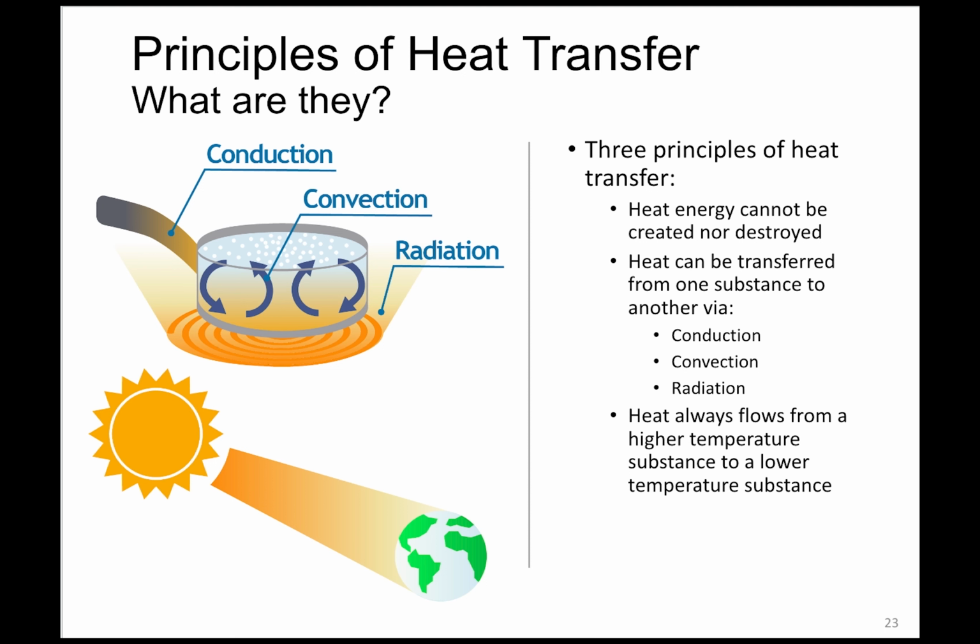In the winter, heat escapes through the home's envelope. Warm inside air comes in direct contact with the inside wall and warms the wall by conduction. The heat travels through the wall by conduction, then through the insulation by conduction, then to the outside wall, and finally from the outside wall to the air outside, all by conduction.